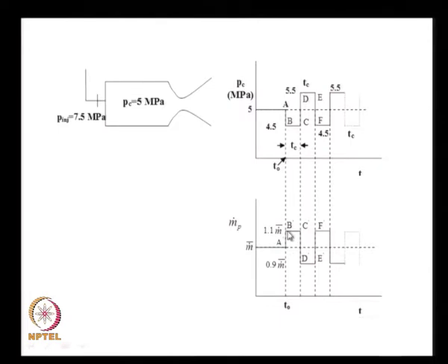In other words, during this time additional propellant has flowed into the chamber, and when the pressure has gone up, the pressure drop across the injector has now decreased, therefore less quantity of propellant now flows and burns. After some particular time a little less pressure is generated and we got a pressure oscillation like this.